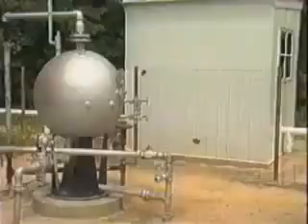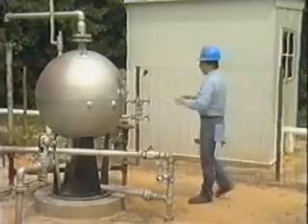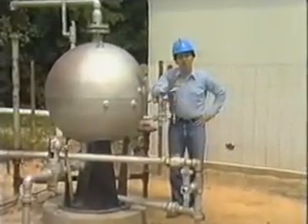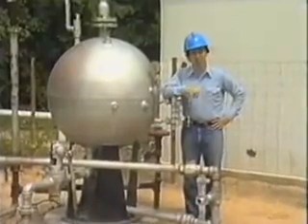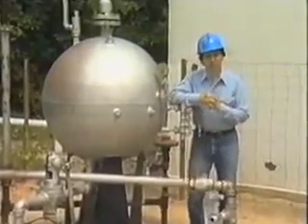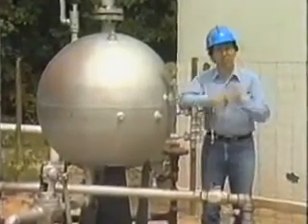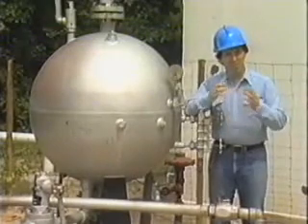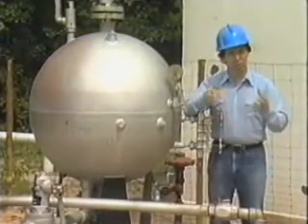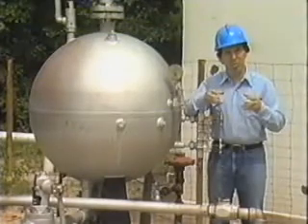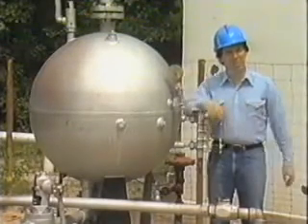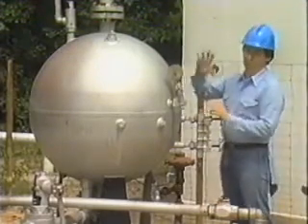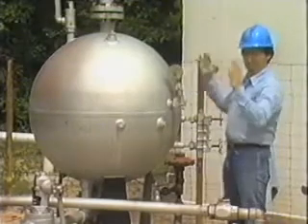Let's have a look at one now. Well, this separator is quite a bit smaller than the cylindrical type, and it is this compactness which is the spherical separator's best feature. It provides good gas separation and liquid handling in a limited space. However, when the well stream contains excess mud or sand or is subject to surging or foamy components, the spherical separator is not economical.